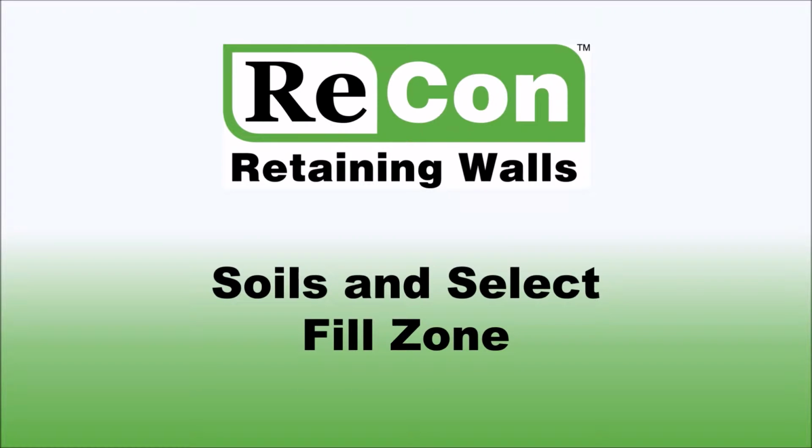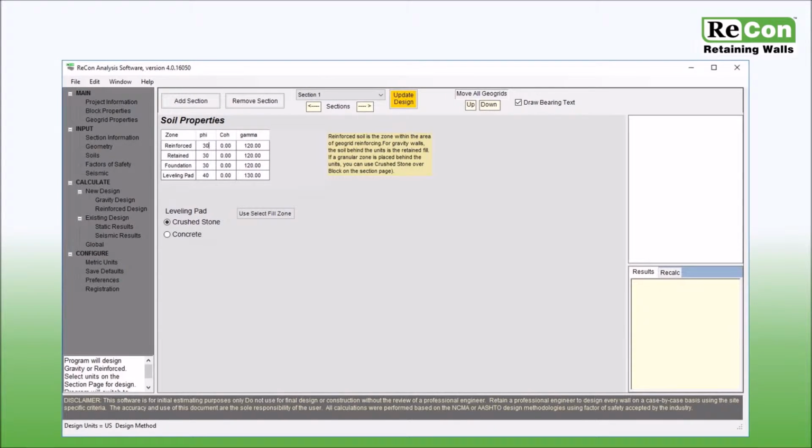In this video, I will explain the process for inputting your soil parameters and using the Select Fill Zone feature within Recon Wall 4.0. To begin, click on Soils from the side menu to bring up the Soils input screen. Near the top, the Soils screen contains a table of soil properties for various soil zones.